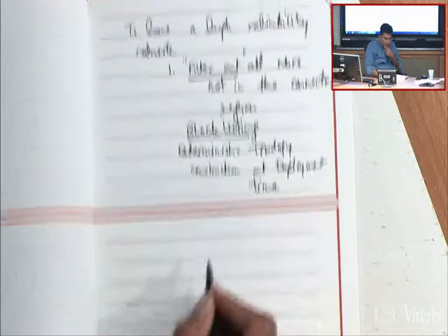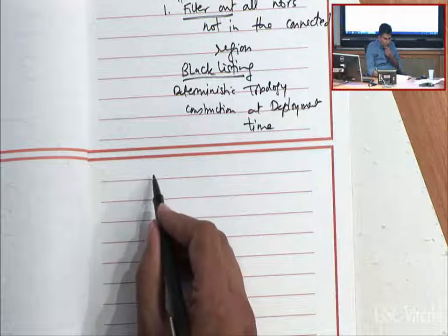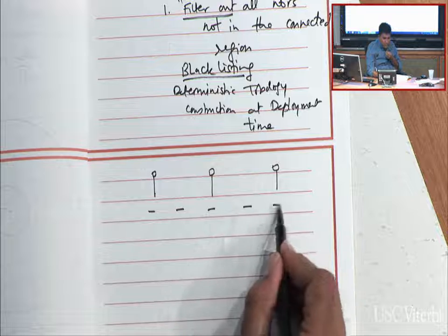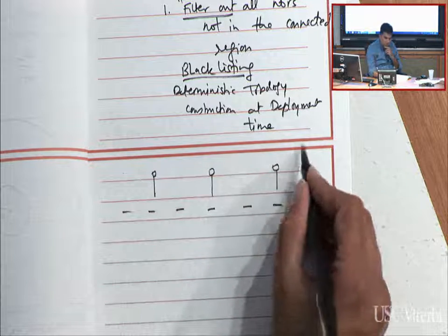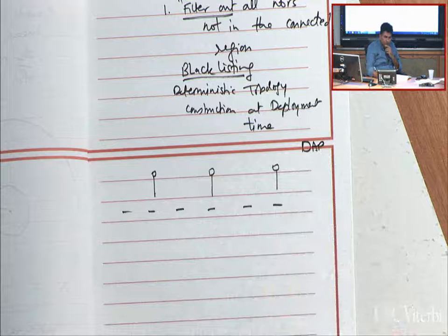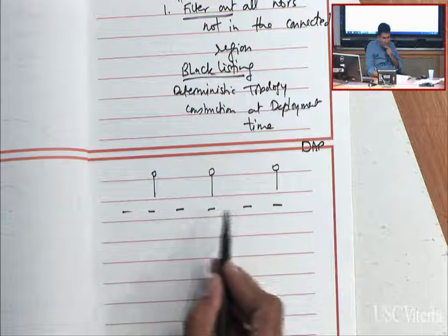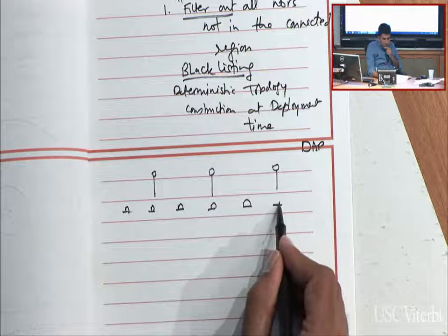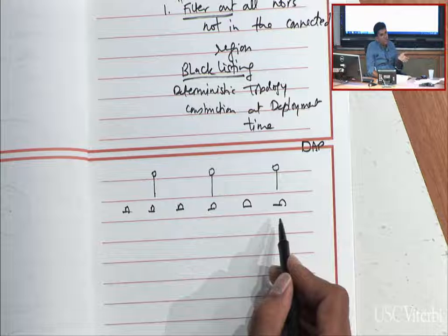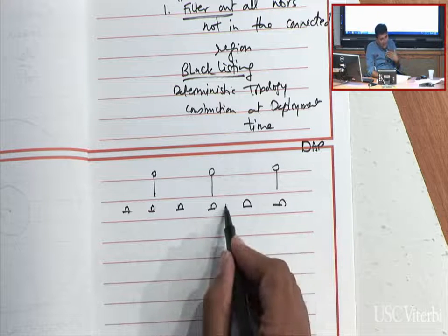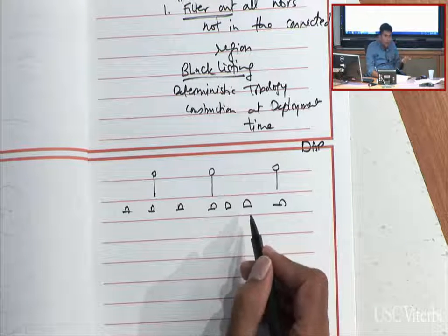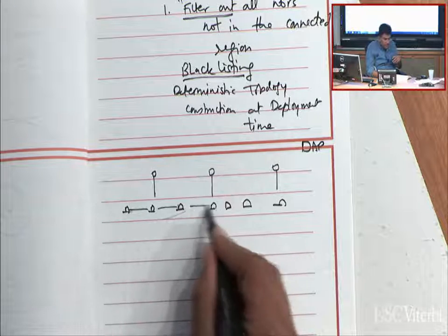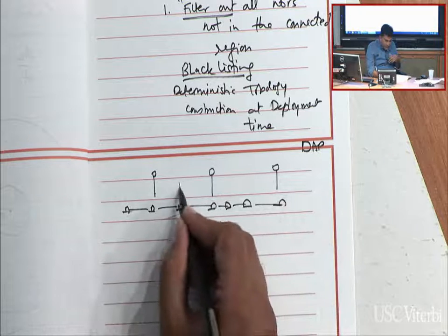So what I might do is say that the network I want to deploy has to have these 3 parking meters and these 6 parking spots all connected to an access point over here. I can make sure that these distances are such that, if I put these nodes down, the link quality is sufficiently high. If for any reason it's not, I might deploy additional nodes when I'm deploying to make sure that each node has at least 1 or 2 highly reliable neighbors to send their data through, and place additional nodes as needed.